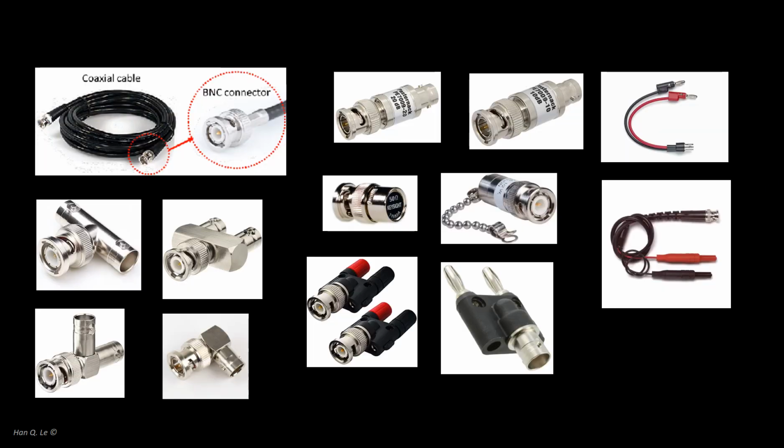The lab work in this step aims for practical, manual experience. In the lab, you will start handling coaxial cables and practicing connecting and disconnecting them to and from instruments. Gain manual familiarity with the connector type known as BNC, which stands for British Naval Connector. Use structures such as elbows, T-splitters, 50 ohm or short terminators, and attenuators if available.